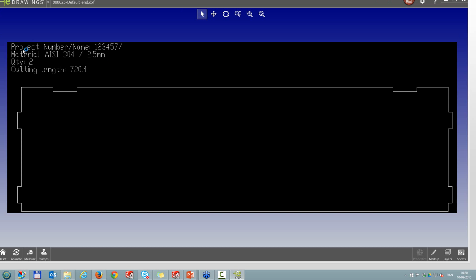But when you are doing these simple DXF files, whoever is going to receive this for processing would then require the bill of material as well. So just to rule out any confusion, we can add the quantity, for instance, in this one. And also we can provide the cutting length for the required profile in this case. So the cutting length times 2, and then anyone running the laser would know how much time that would take to do.